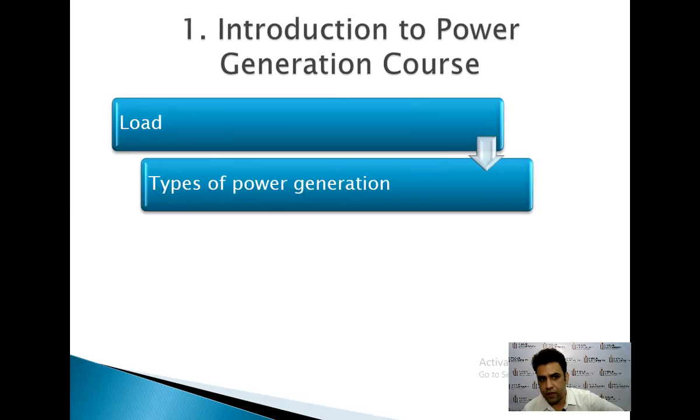After I know my load, after I predict my load, the next step is I will choose the power generation type, whether I need to install a wind power plant or a solar. It's better for solar. For solar, I will do calculations and cost analysis. Of course, solar is costly. So I will also look at my resources and whether I can afford the oil power station, the generation through oil, we call it a diesel power station, or